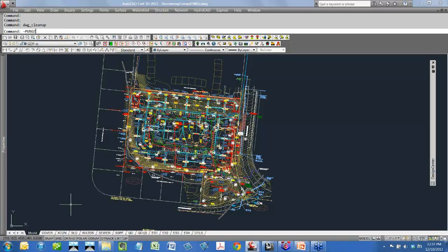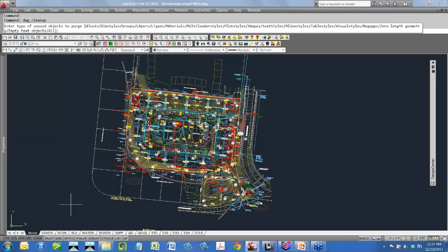So if you learned AutoCAD back when I did, when we typed purge at the command line, there were no dialog boxes really to speak of, and it brought up purge at the command line. So one thing you can type here is just an A for all, and it more or less runs through what the dialog box did. But there are a few things, actually I guess maybe just one now, in other versions until they added that last checkbox to the purge dialog.